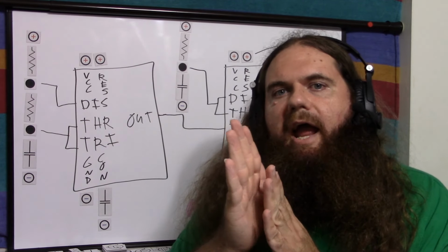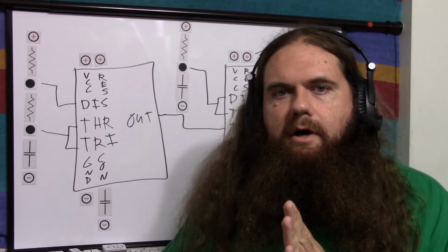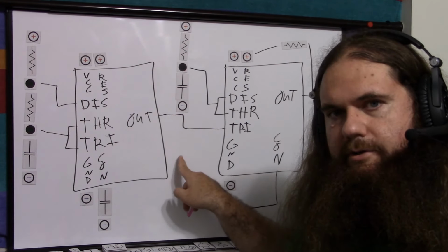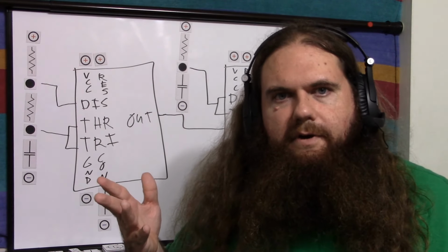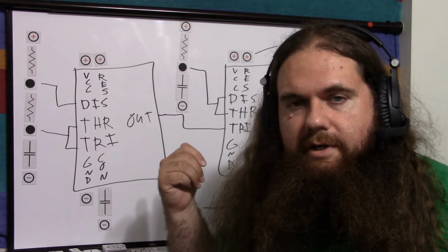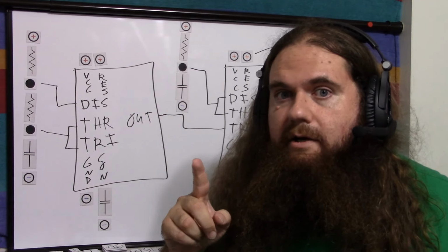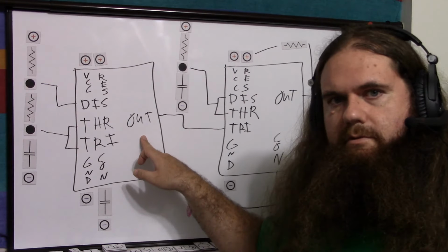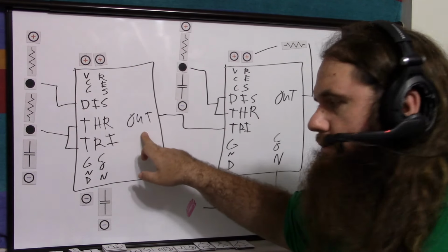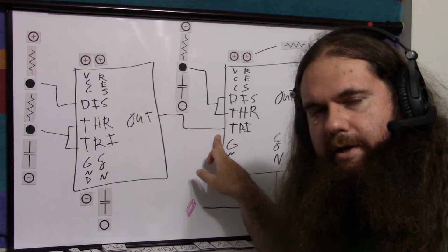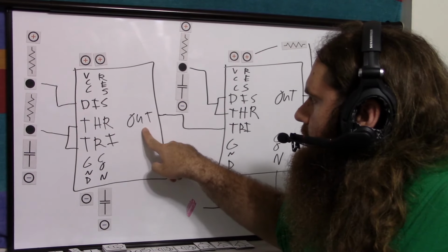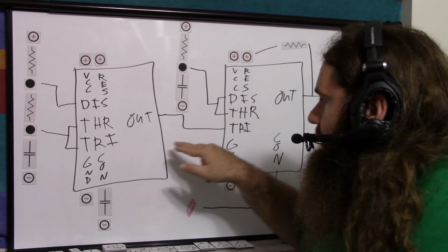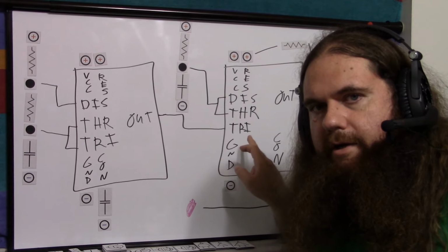But if you're holding the trigger after the timer is trying to turn off, if this monostable is trying to go low and you're still holding trigger, you're not letting it. It's undefined behavior. Usually, it's just going to stay on until you let go, but that's not a 100% guarantee. But in any case, you're not going to get the result you want. The low time here, right? When output here goes low, trigger here turns the timer on. So if this tries to turn off, but this is still low, it hasn't gone back high yet, then you're still going to be getting the high end of your pulse.